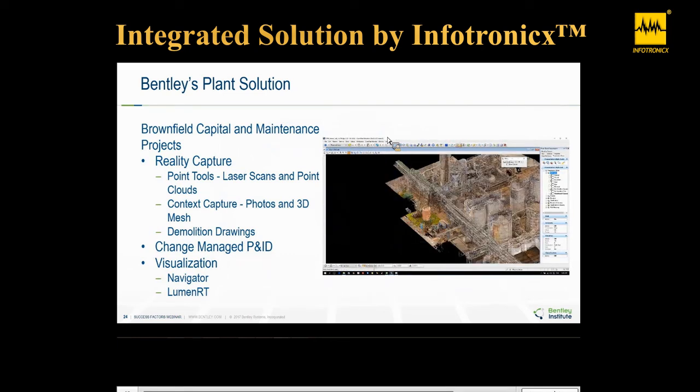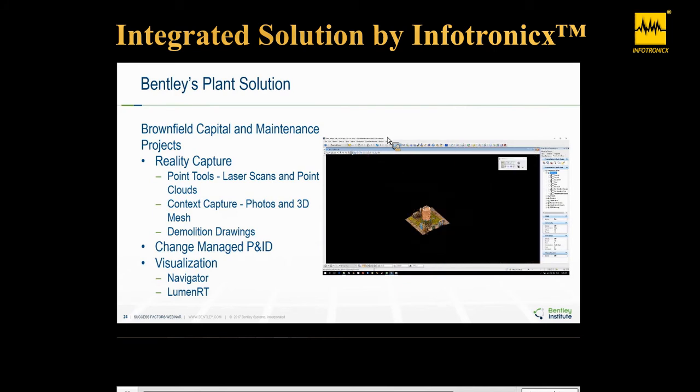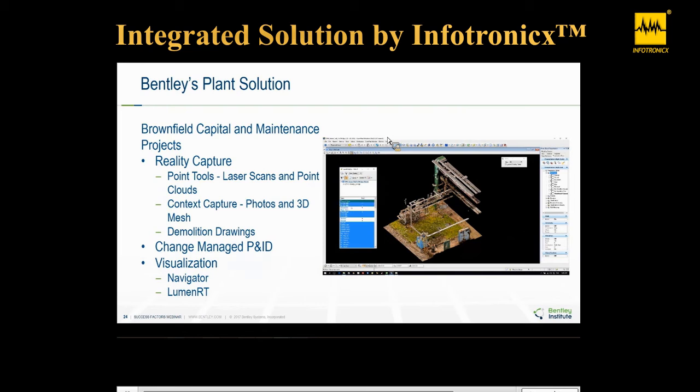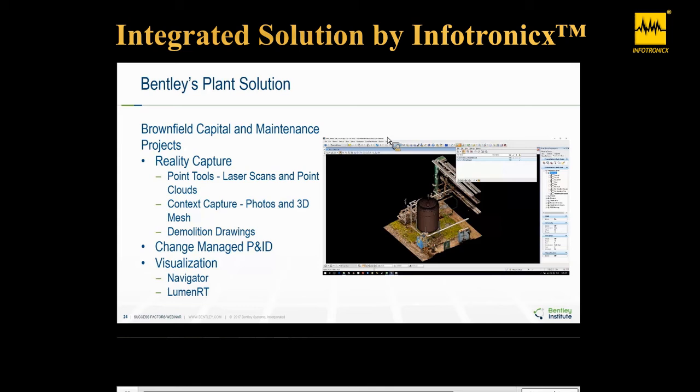As a plant owner, most of the project work involves some existing equipment. Bentley's plant design solution accommodates field rework in a few ways. Using reality capture technology, we can now minimize survey work with point clouds or photos. The resulting 3D models are dimensionally accurate and reflect the current plant component. For this, we can produce field drawings such as dimensionally accurate demolition drawings or final arrangement drawings.